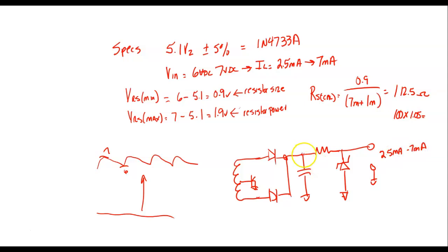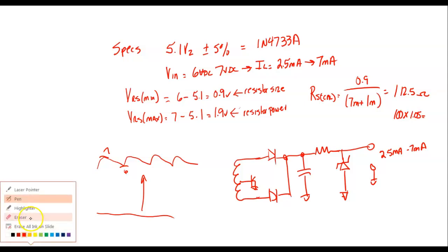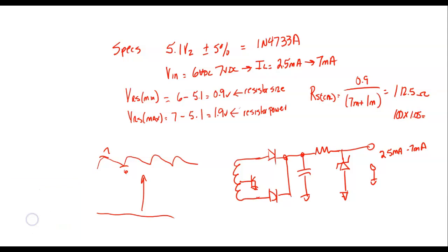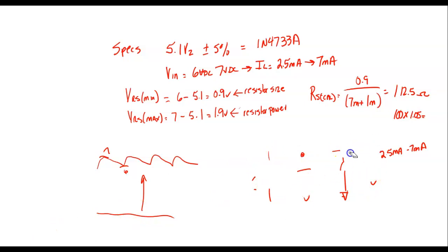Now, the problem is before I hook up the circuit, I want to verify my circuit. So instead of depending on this unregulated DC, I'm going to use a DC power supply so I can actually set the limits, right? So I can set the current and I can set the limits. So my test circuit, before I start building hundreds of these things, is going to be this.